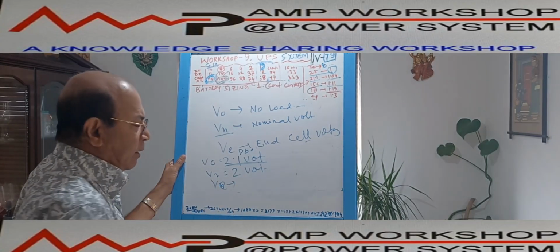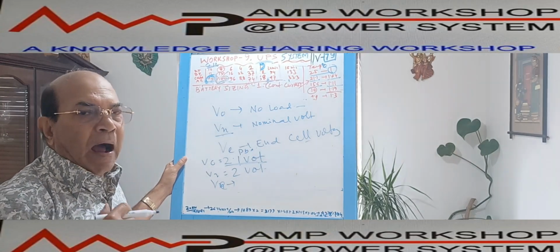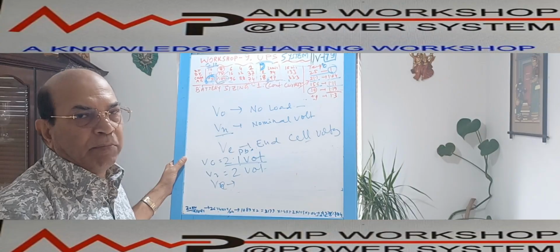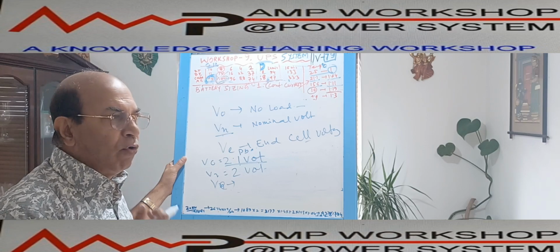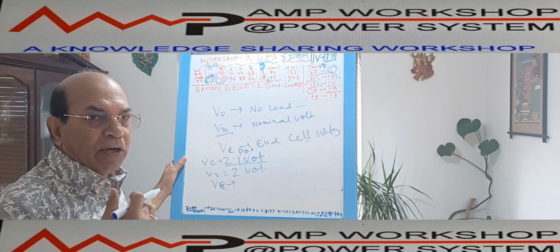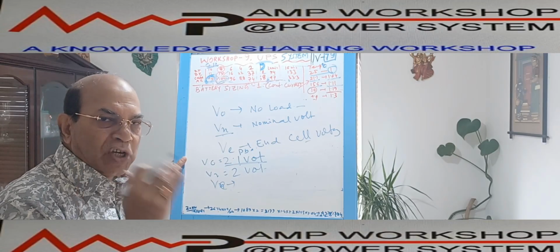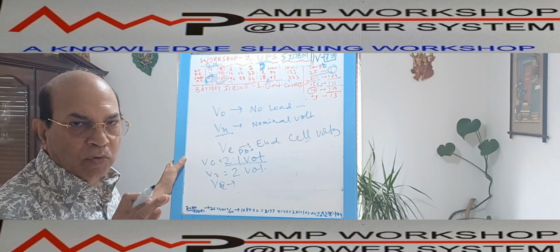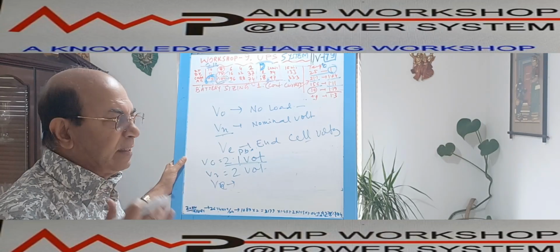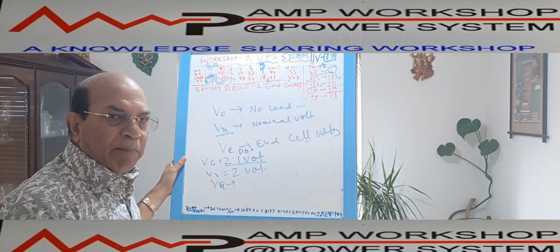for the lead acid battery, normally we do not allow the discharge of the battery after 10% of the voltage drop. It depends on the load requirement. If the load is very sensitive, it cannot take more than 5% voltage drop, then we have to stop the battery discharging at 5% drop. But if the load is slightly less sensitive and it can accept the rated voltage below 10%, then we can allow up to 10% voltage drop.